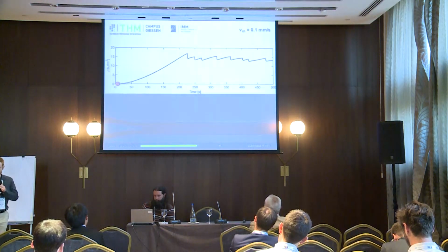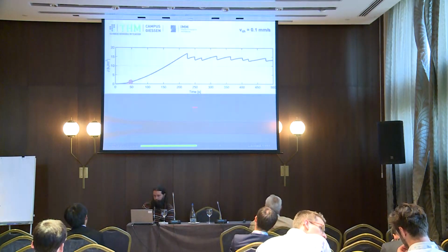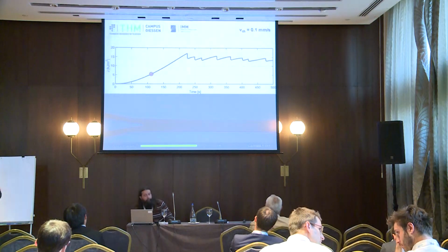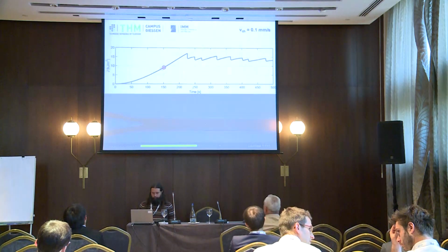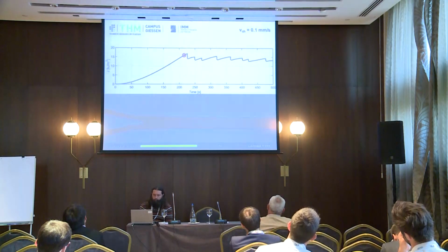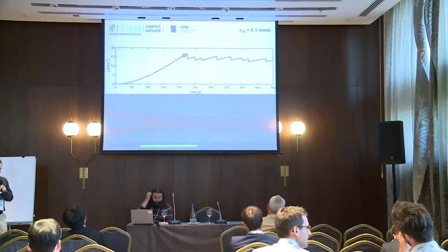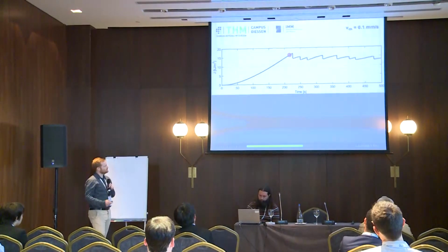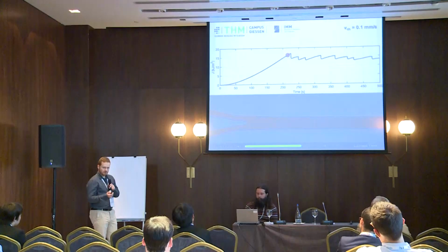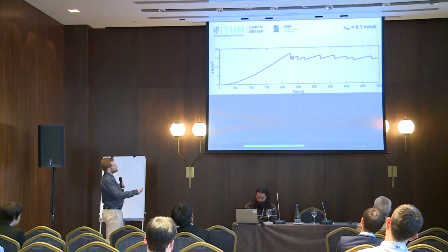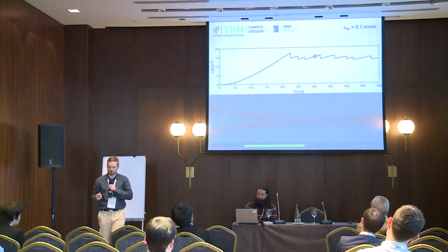We are increasing the test speed. You see again J over time. Pre-crack gets visible. And distinctive blunting appears. Crack tip is necking. And now we had a marginally subcritical crack growth again. And we're at the point of maximum J. The crack propagation turns over to overcritical, but this appears here many times. So we have here distinctive stick-slip fracture.